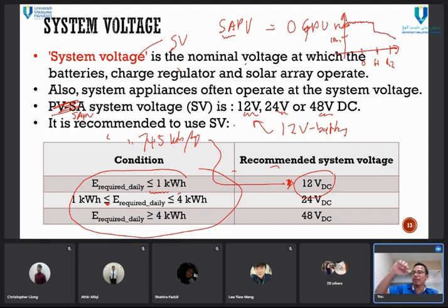And then over time it will drop like that. That is the pattern of the battery. If you measure the voltage, you can check if you don't trust me. But if you use more load in the first place, when we multiply the loads, it will go down more because the amperes is more and it will drop more. So imagine if you use 2 kilowatt hours of load but a 10 volt battery, it will easily reach the bottom level and cut out. Then the charge controller will automatically turn off because of over-discharge protection. That's why the battery is off, not dead.